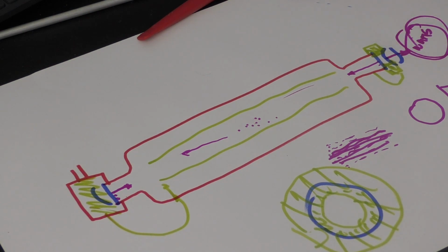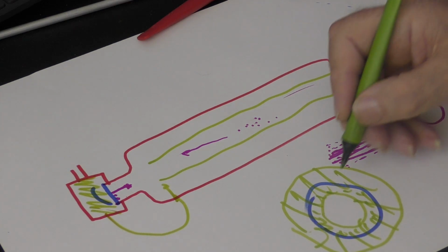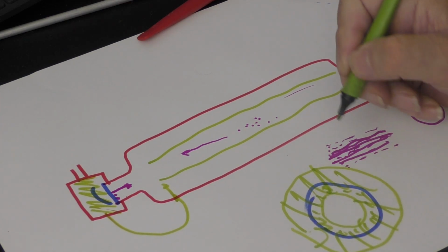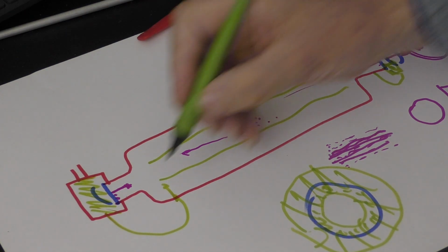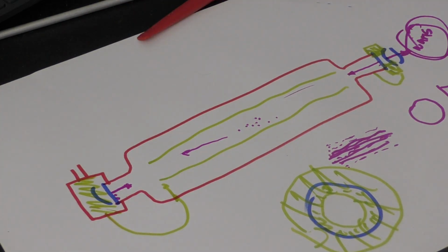Do we think that mirror is going to stay flat if you subject this to an instant shock load of cold water? Well, the answer is no. So consequently, we're going to get a distorted mirror like this, and we're going to have a lot more of these photons that don't actually make it on their back and forward return journey. So we're not going to get the correct amount of power out of this tube while this mirror is distorted.